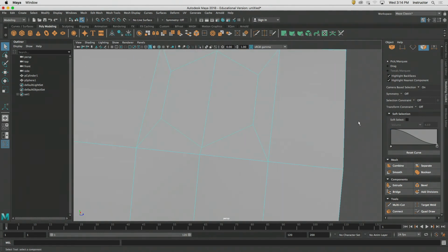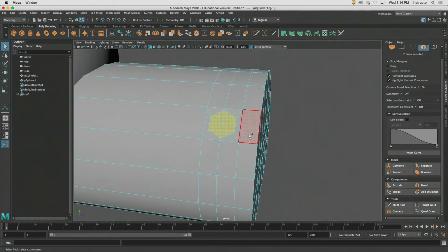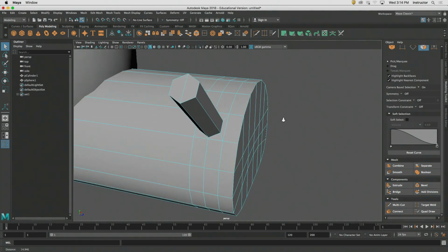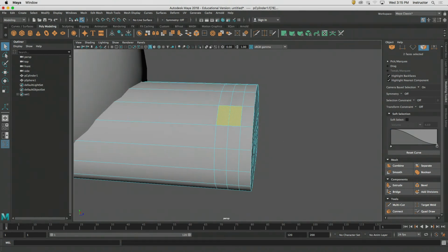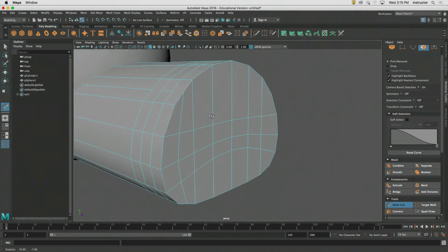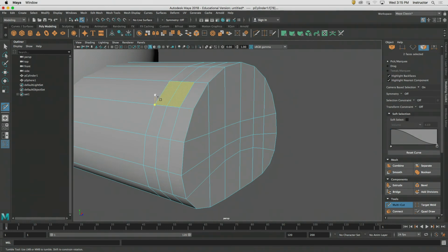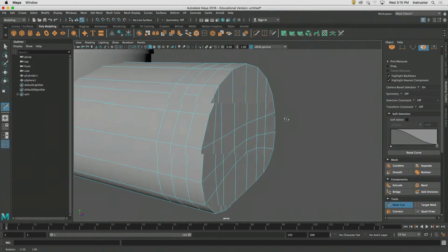Now, if I go back to my selection tool, I have something that I can begin to extrude out that will look a little bit more representative to what I'm after. Okay. Circularize, which is pretty cool. Yeah, it's a good one. You know, another thing that you could do before you run Circularize is, I'm just going to use this with multi-cut. There we go. Yeah, you could slice in another, the location of that's not going to work given the flow of this, but you could put another one in here, like that. There we go.